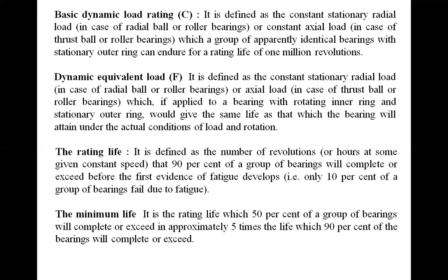Okay. So in that, one term is there. What is the rating life? In that rating life of 1 million revolutions, what is the rating life? The rating life is defined as the number of revolutions that 90% of a group of bearings will complete without failure.